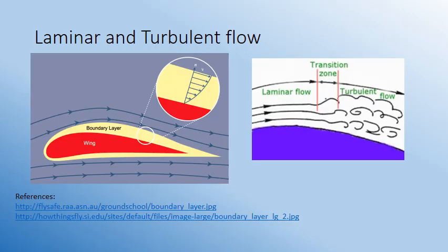The boundary layer of an aircraft wing is the area of airflow that is extremely close to the wing where the effects of viscosity become significant. Two different types of flow occur in the boundary layer: laminar and turbulent flow. Laminar flow is parallel to the surface of the wing and is very smooth, whereas turbulent flow contains many swirls and often results in much more skin friction drag. However, laminar flow is much more difficult to maintain and is unstable. Therefore, once the air travels far enough down the surface of the wing, the flow will become more turbulent, resulting in more skin friction drag.